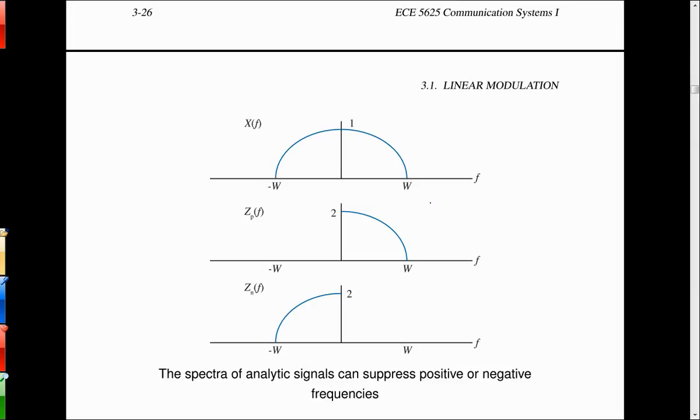Because if you have certain types of sampling front ends for radio signals, if you have to have two A to Ds, one of the issues that comes up is the matching of the A to Ds. Will they be perfectly matched? They won't be. And will they be matched over temperature? They won't be.